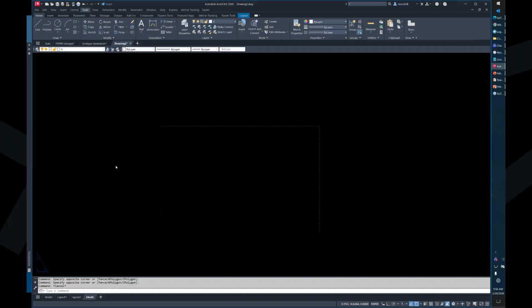We seem to have an issue plotting fence line types through the sheet set. Typically, we have to start Civil 3D in order to get the line types to plot correctly. Scott, that becomes a bigger question: are you plotting sheet sets in the web? If you're plotting sheet sets through the web in ACC, you have to have the SHXs uploaded to your web.autocad.com account, and I have a blog on that too.